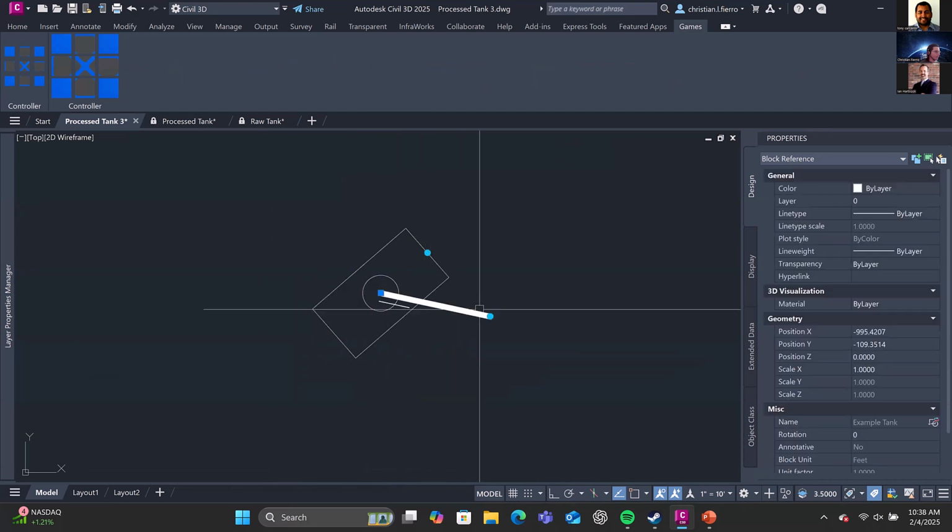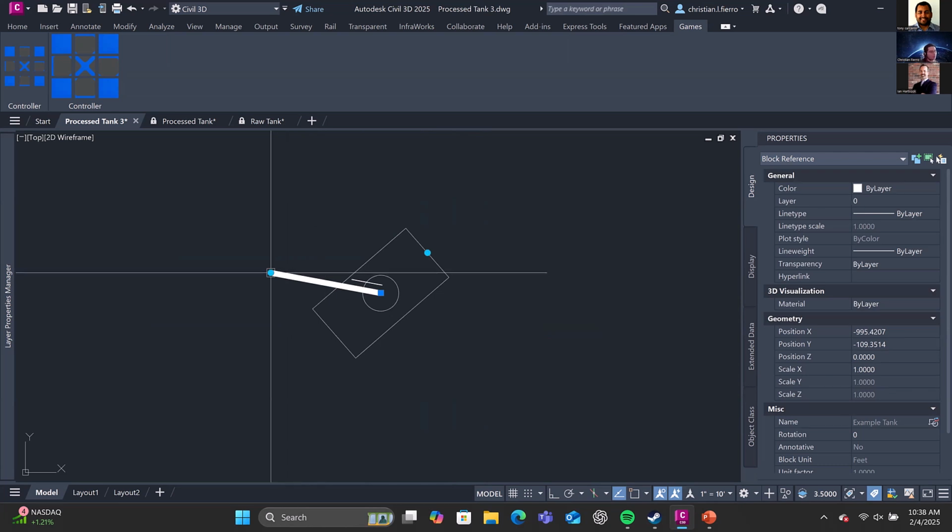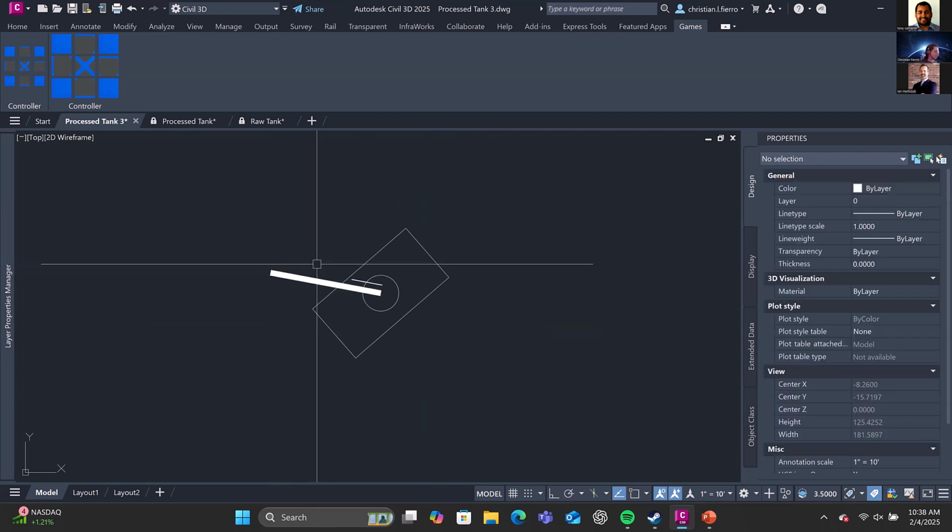And whenever I rotate any of these here, these nodes aren't rotating separately as well. Some dynamic blocks you'll see whenever you use some rotation parameters or different move parameters, you're going to start noticing a lot of other parameters start moving. That's because whenever an object is being moved, the parameter is not referencing that object or parameter itself.